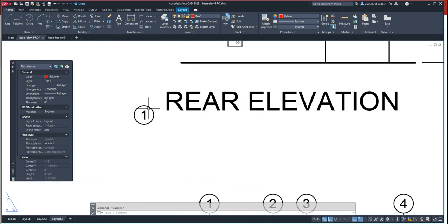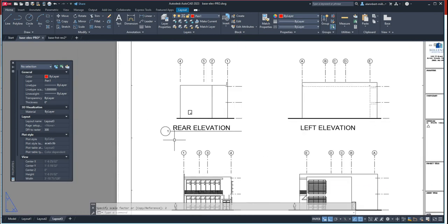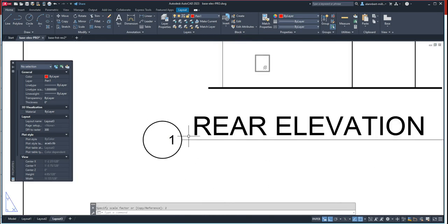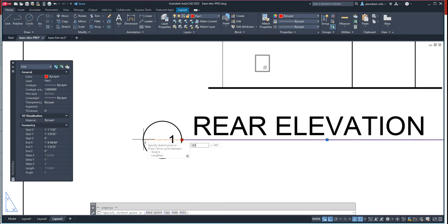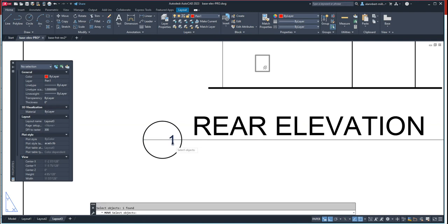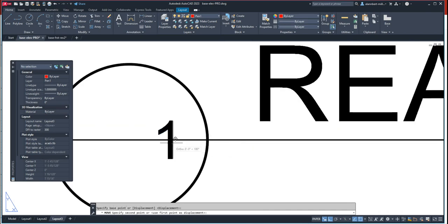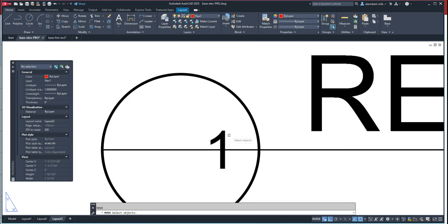This one is a little bit too small, so you would maybe have to scale this up to twice. Then we would draw this line, go through, and then move this. Let's move the text on the insertion point. INS doesn't seem to capture, so let's just manually move that there.